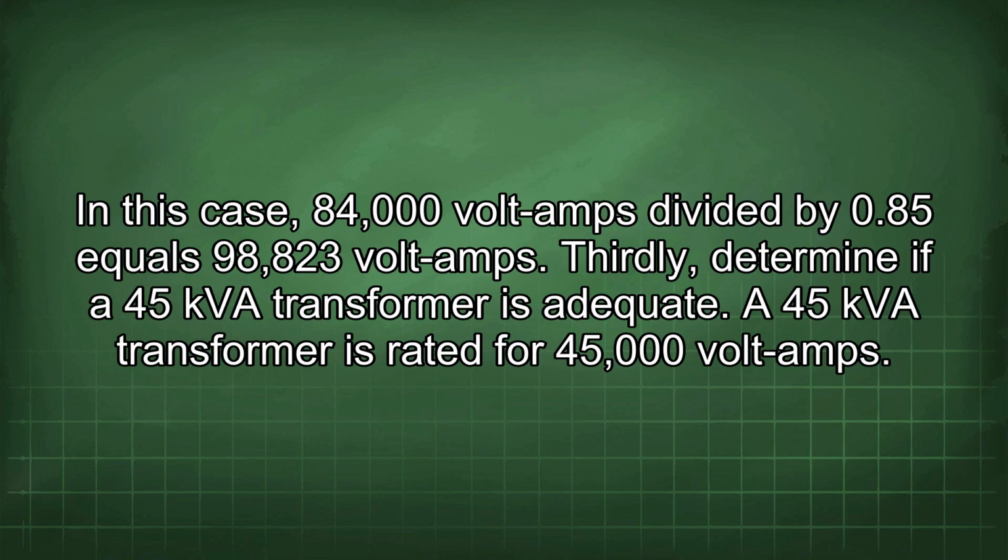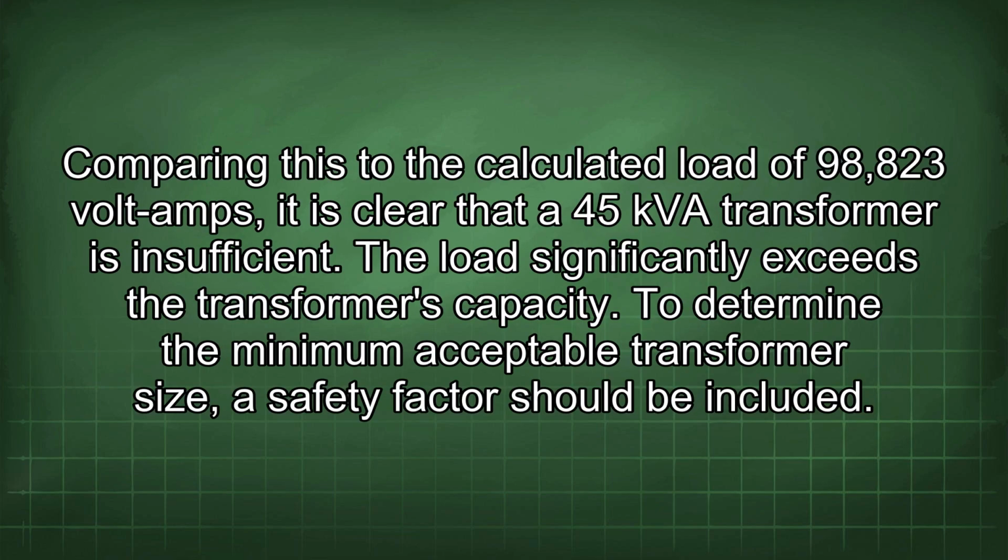Thirdly, determine if a 45 kVA transformer is adequate. A 45 kVA transformer is rated for 45,000 volt-amps. Comparing this to the calculated load of 98,823 volt-amps, it is clear that a 45 kVA transformer is insufficient. The load significantly exceeds the transformer's capacity.